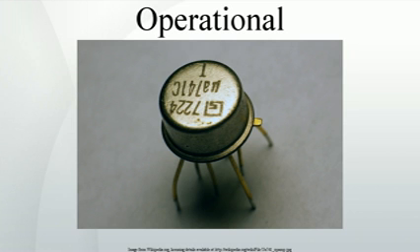Output amplifier. In the circuit involving Q16, variously named rubber diode or VBE multiplier, the 4.5 kΩ resistor must be conducting about 100 µA, with the Q16 VBE roughly 700 mV. Then the VCB must be about 0.45 V and VCE about 1.0 V. Because the Q16 collector is driven by a current source and the Q16 emitter drives into the Q19 collector current sink, the Q16 transistor establishes a voltage difference between Q14 base and Q20 base of 1 V, regardless of the common mode voltage of Q14/Q20 base.